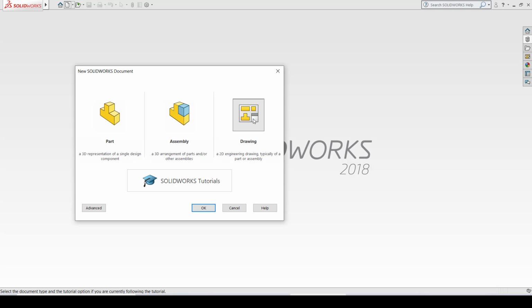You can use either first angle or third angle projection as per your design requirement or company requirement. You can select those projections and place all the views of the different components or drawings, like the front view, top view, isometric view, bottom view, back view and side views. All those views can be seen in the drawing module of this software.